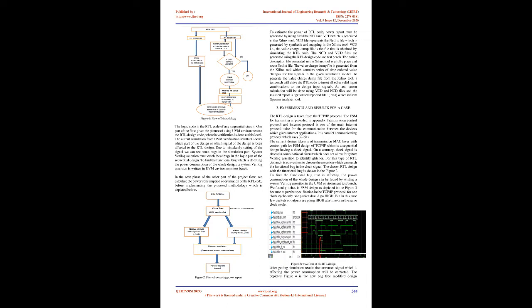The verification process can be improved by using pseudo-random verification instead of a direct testing approach. The main question was how to make such transactions effective, and it is by adopting an existing methodology that supports pseudo-random verification. It provides consistency and uniformity in the way verification components are developed, used, and connected. So for a new learner who joins a team, the ramp-up time will be reduced. Code is reused more, usage is less, and bugs can be seen.